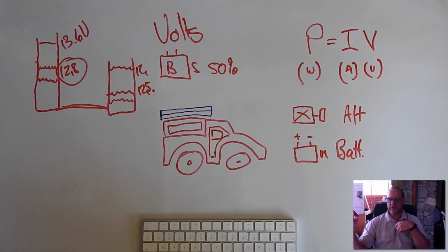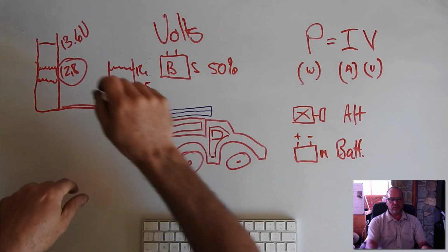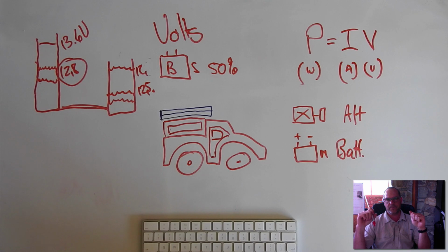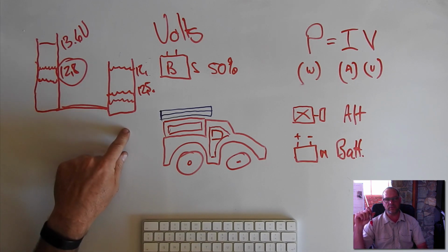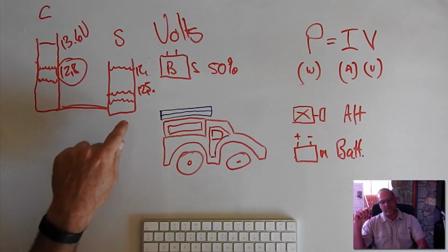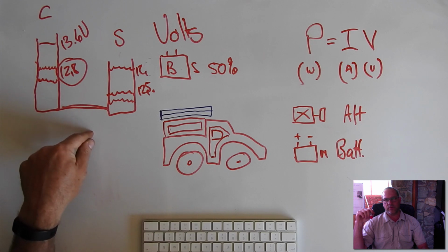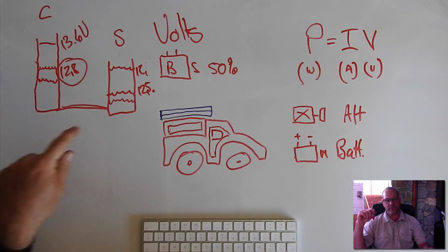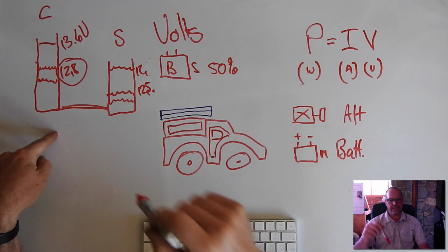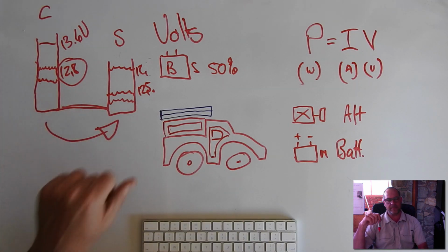It means in real terms, and it happened with one of my guys in the group before, that he connects the two batteries with the manual switch because his fridge is running low. So this is your car battery and this is your secondary battery. When he starts his vehicle in the morning, he flips a switch to connect the two batteries, and the car battery is now sending power over to the secondary battery.